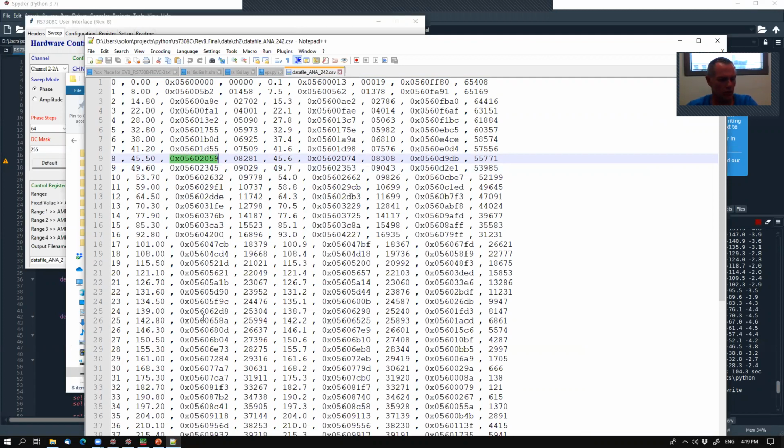So this is an error that applies to both sources of errors. We wanted to remove at least the quantization noise, especially if you do a frequency phase sweep with very small steps, for example, 0.5 degree steps. The quantization noise can be higher than your actual phase step.